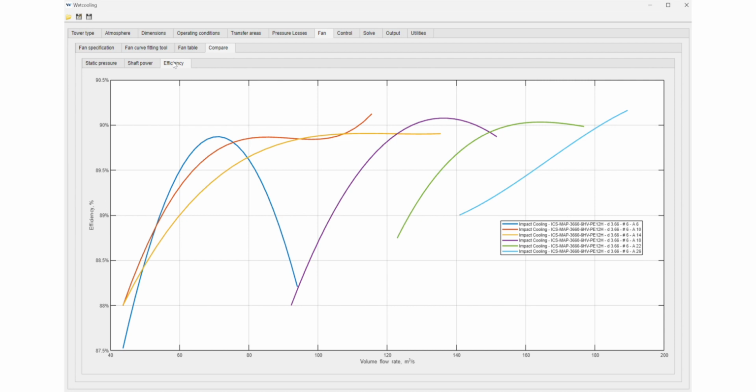Generally, when you obtain fan curves from fan manufacturers, it will give you all the fan curves with a certain number of blades, with a certain diameter, but where the angle varies from the smallest to the highest. And there you can see if the fan curves display that on the fan curve, so that you've entered all of the polynomials correctly.